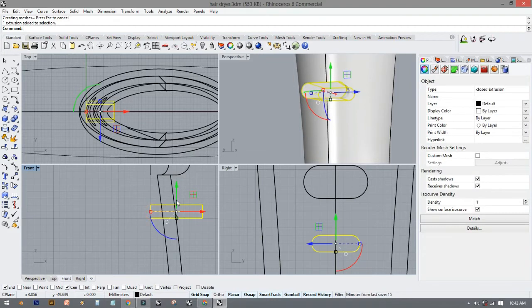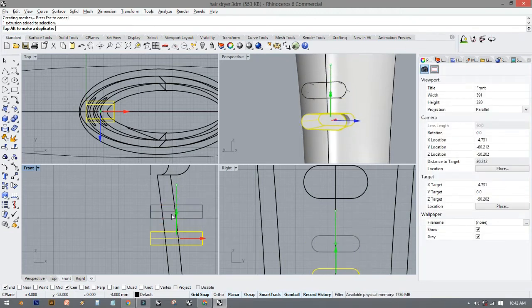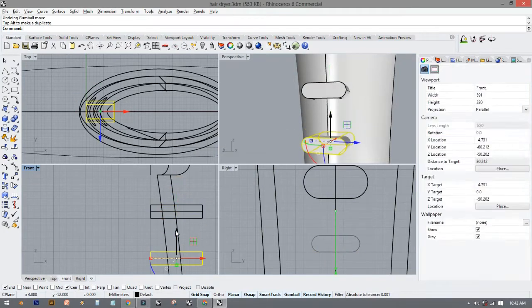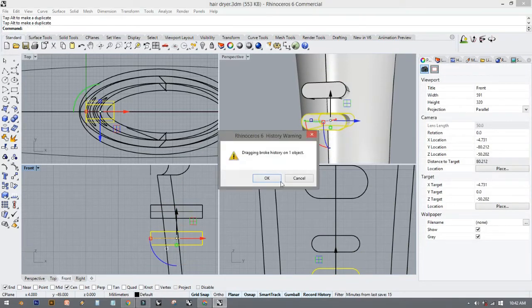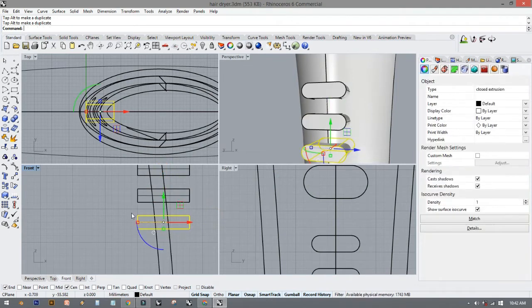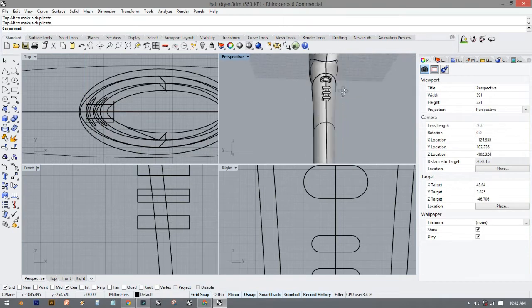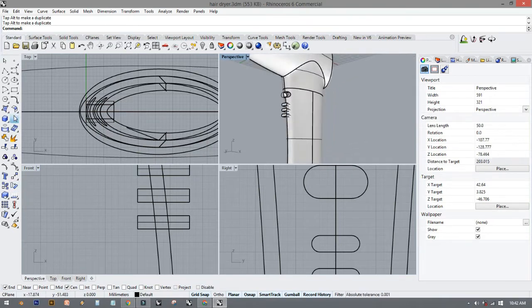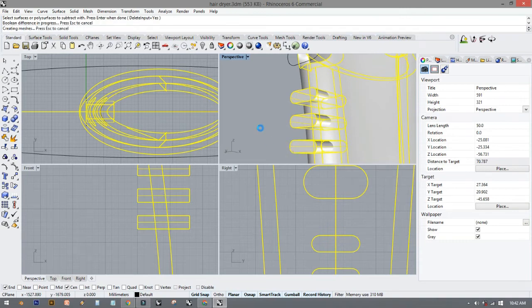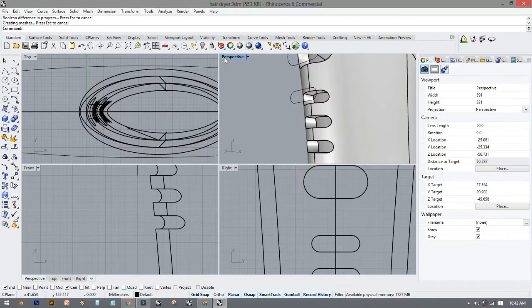So this one is a switch, so I will just copy it. To copy this part, you can click on this and get this arrow, and then while you're dragging it, you press alt. This is a very fast way to copy an object in Rhino. So let's see the button position. I think it's nice. And then we can do the difference. There you go. No worries.